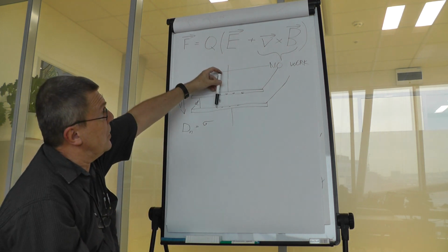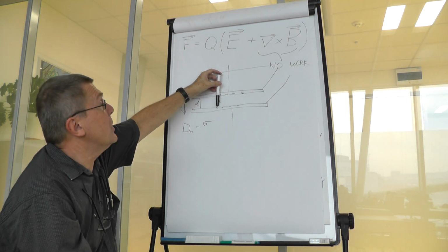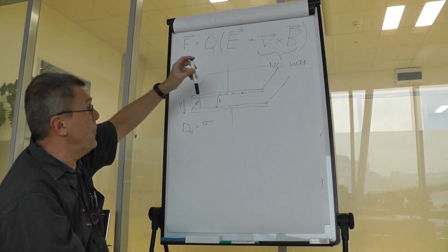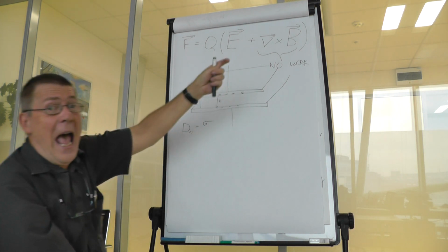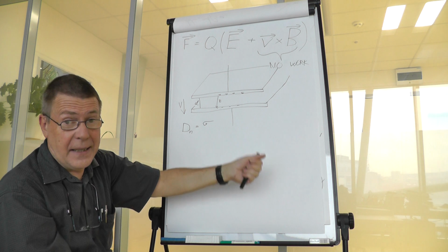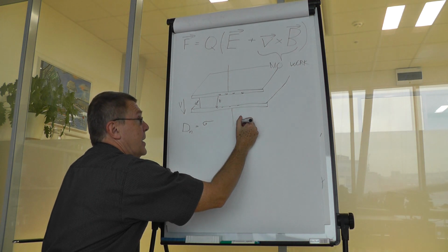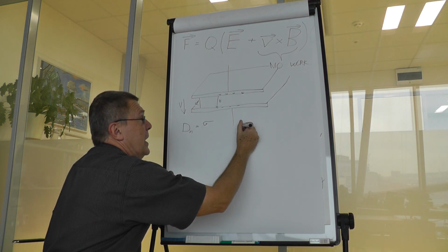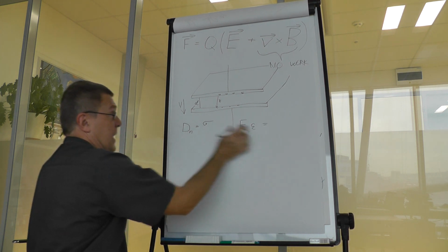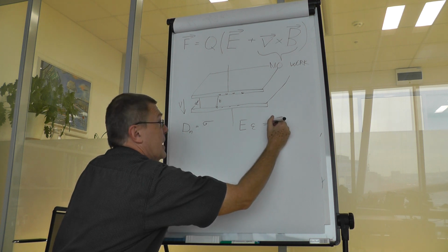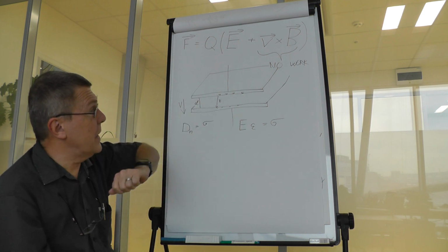Well, in the case that the material in the capacitor is isotropic, the direction of both components, I mean electric flux density and electric field strength, are identical, they are collinear, then we could put down that E multiplied by permittivity, which is D, is equivalent to the charge density on the surface of the electrode.